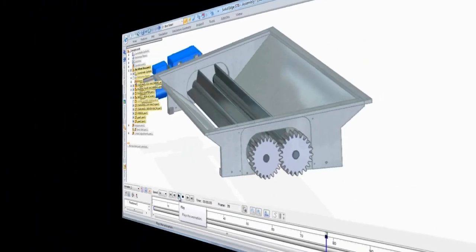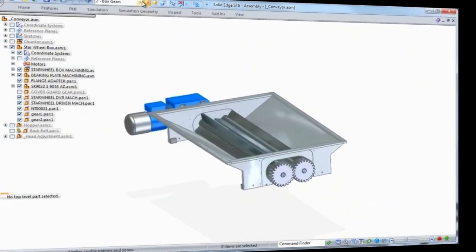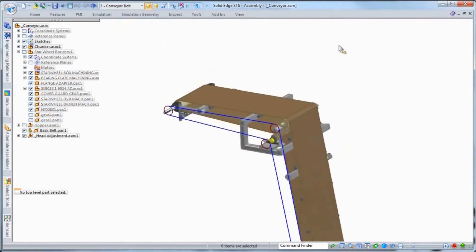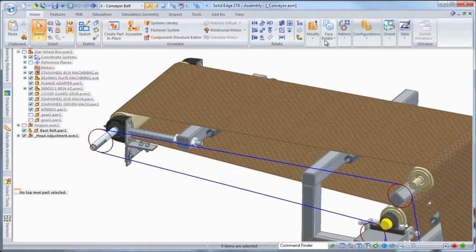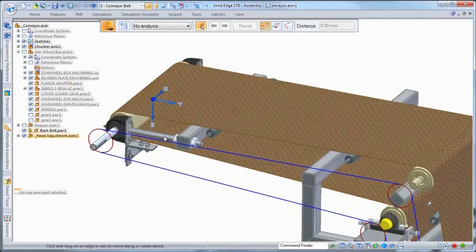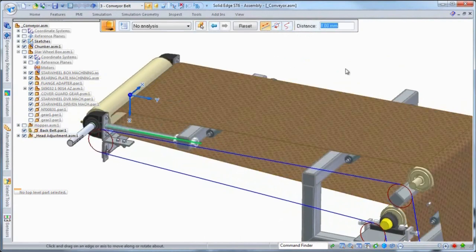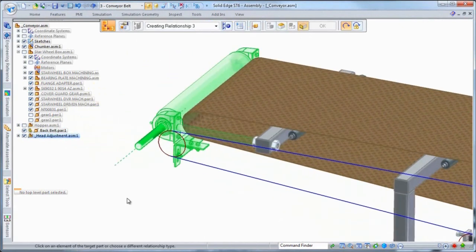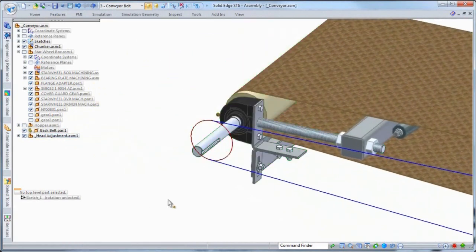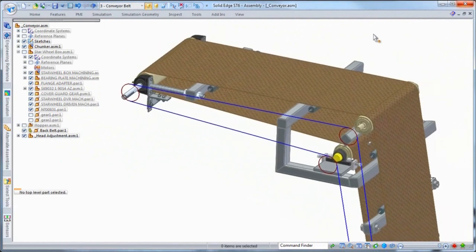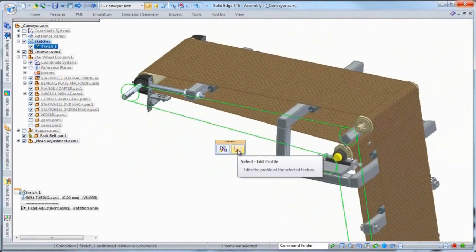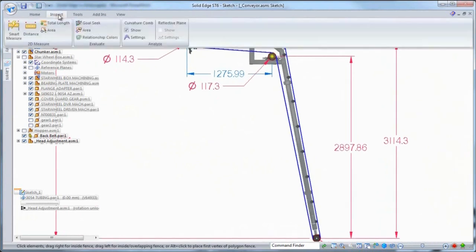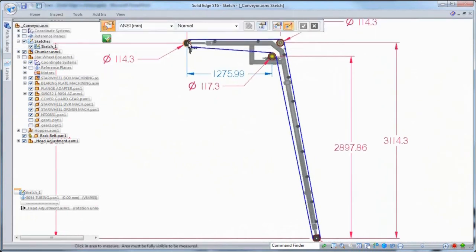And it does. Another type of off-the-shelf part is a belt. We know that whenever you buy belts, you buy them in certain lengths. Well, inside of Solid Edge, what we can do is we can assign assembly parts to 2D sketches. Why is that? Well, basically we have a tool inside of Solid Edge called GoalSeek. GoalSeek is monitoring how long this belt is for us.